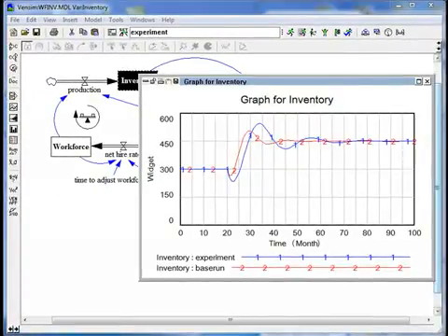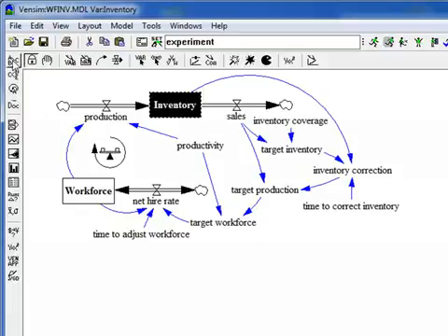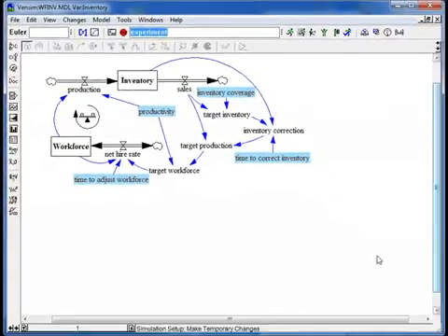So this was what I wanted to show you right now. I hope you gained a little bit of insight into what is possible with WinSim. What are the tools that you can use to see how a system, a model, is behaving: that you can use the tree output, that you can use graphical output or causes strip output as graphical output, that you can use the synthesis button to see it as an overview, and how to change single values when you put here on set, and then you can change single values.